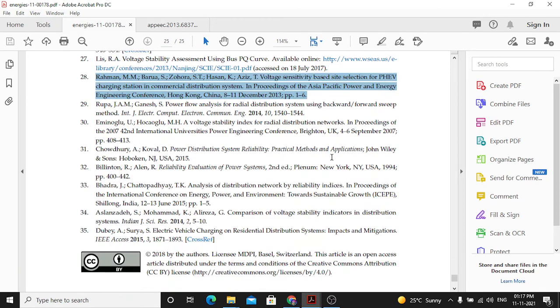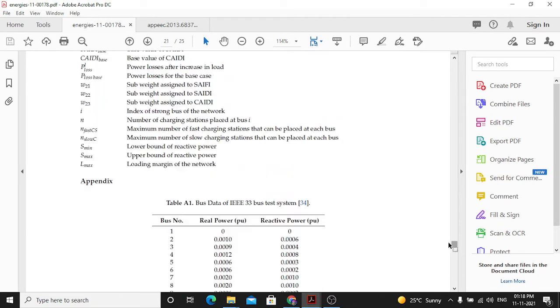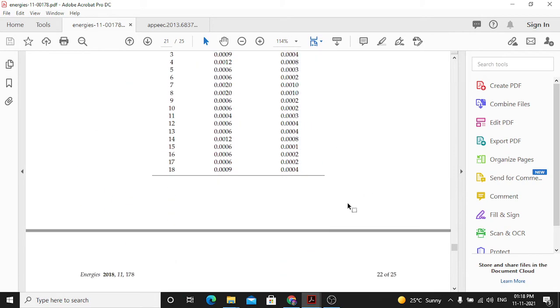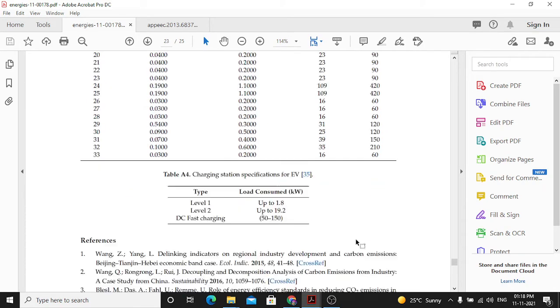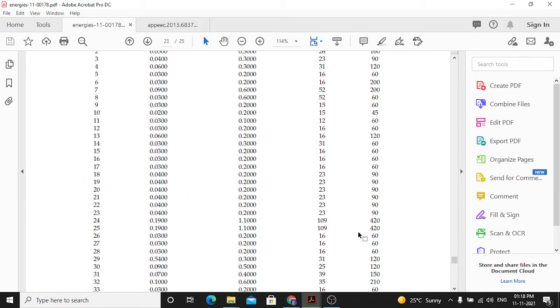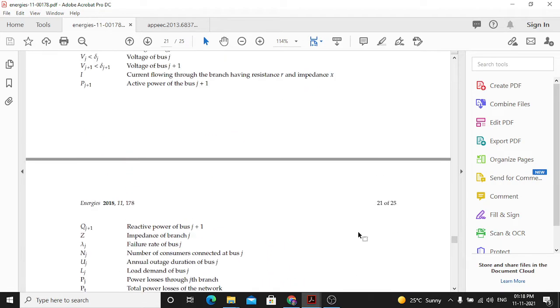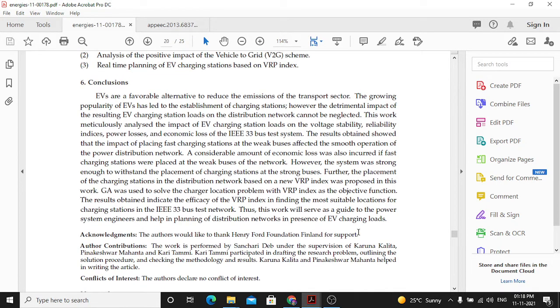Then how can we control that? If, without sensing the rotor position and rotor speed, we can design the control scheme for the rotor side converter, then all the problems associated with the speed sensor control scheme can be overcome. So that's why nowadays researchers are thinking of designing speed sensorless vector control schemes.